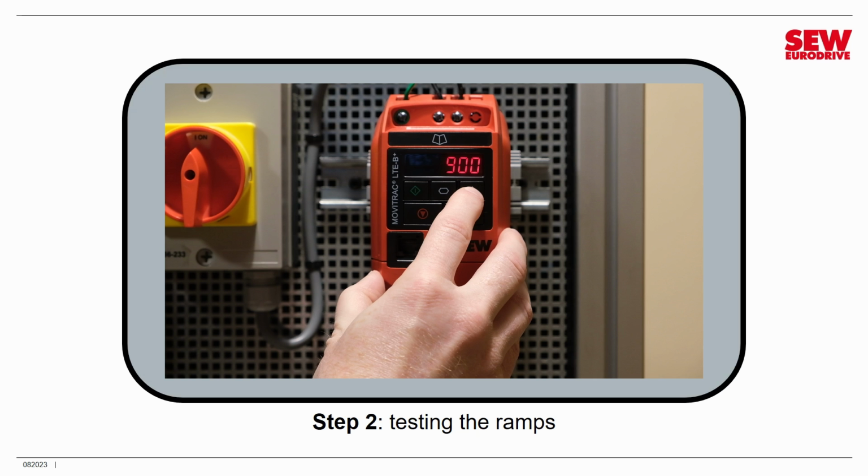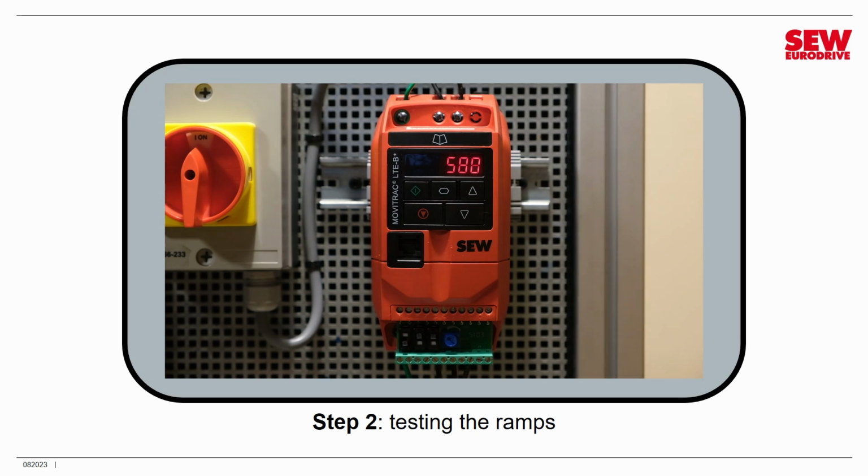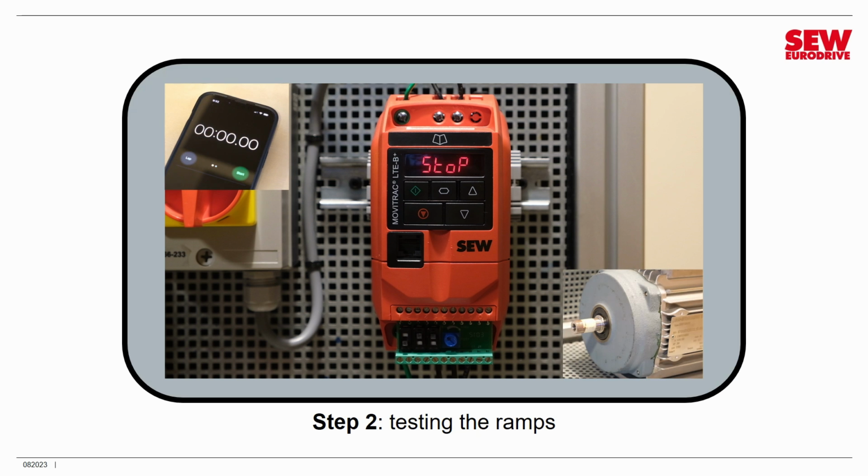Okay, my speed is adjusted. Now I'm going to stop my drive, so I hit stop, let it come down. And then we're going to time our ramps this time. So I'm going to get out my phone and put it on the stopwatch app, and I'm going to hit start, and I'm going to start the stopwatch at the same time, so I'll press both buttons together.